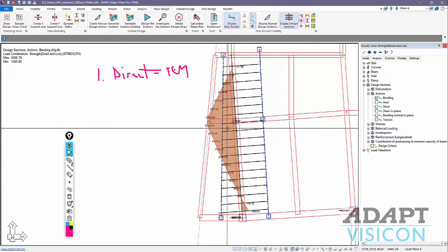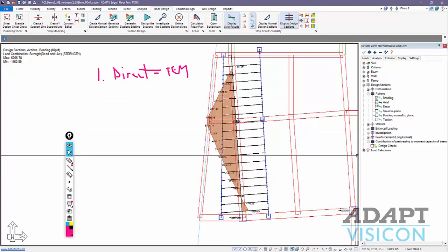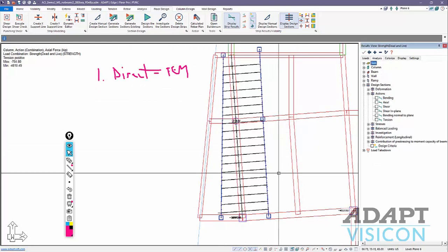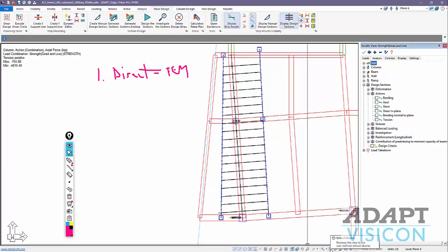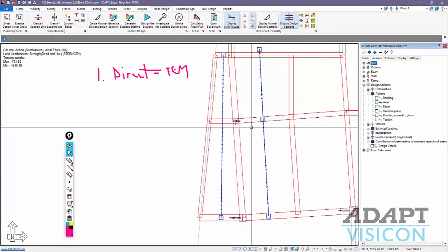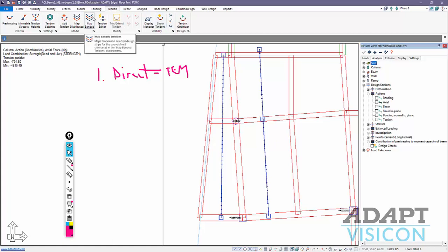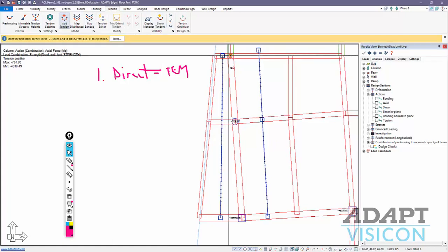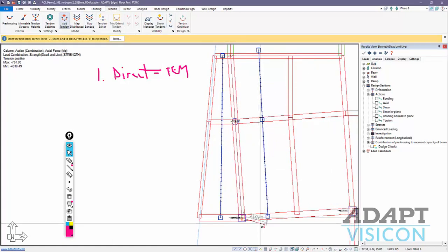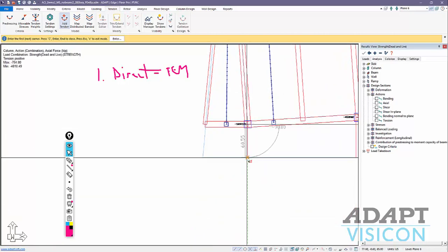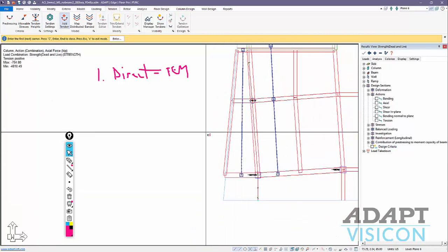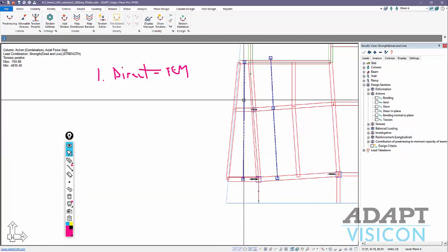Now if we say, well, this beam needs post-tensioning, so we're going to add bonded PT maybe to the beam. In this case, let me just turn off the display of the design cuts. I'm going to go now and add PT. So I'll add a cable from here over to there, and maybe this exits out there. So there's my cable, and if I dimension